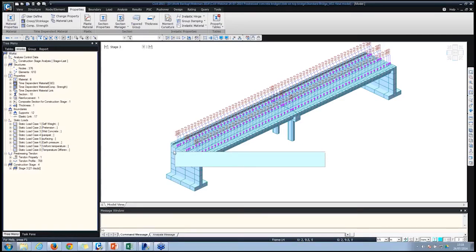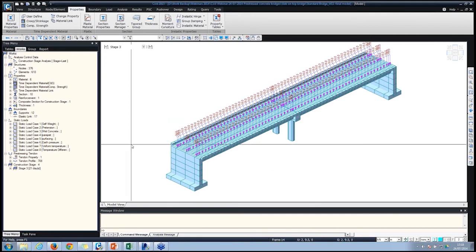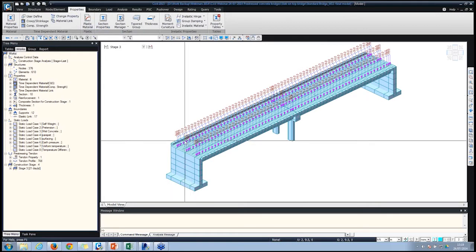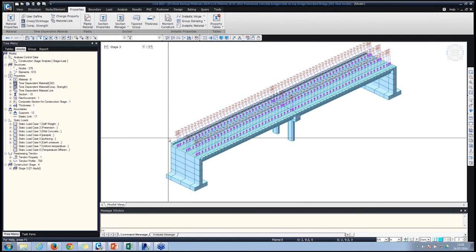Okay, so just to pause here, I've got a few questions I would like to answer. One of our attendees has asked, can the tendon template be used to edit the tendon subsequently? Yeah, as I said, you can save the tendon template input as a tendon file, export it, and then import it back and edit, and then apply it again. And another question is how the top slab is connected to PC beams. Because this is a composite section, it's assumed a rigid connection. But for designing purposes we do check for the interface shear between the slab and the PC beams.